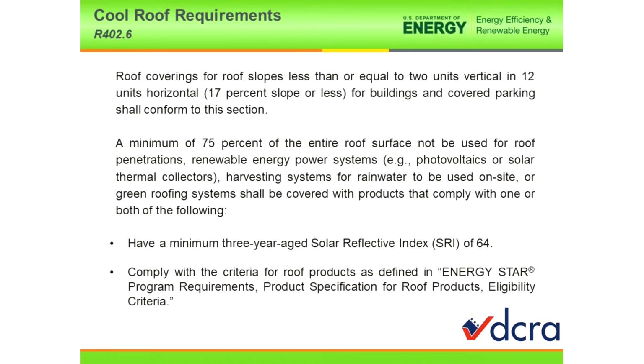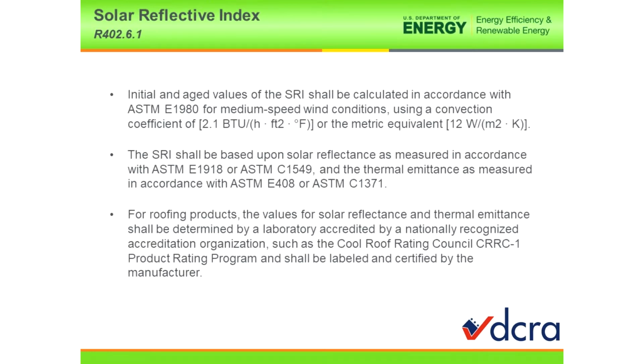So, in order to be compliant with this, we're not going to accept a statement. We need to see your product data for your roof covering that says, in fact, that this particular material has an SRI of 64 or greater, okay? I'm going to say that again. We're not going to accept a "no" for compliance with this. The particular material that you are using to cover your roof must be in compliance with this SRI 64 requirement. So show me a spec sheet, show me the specs for the roof products that you're installing, and we're good. Okay?